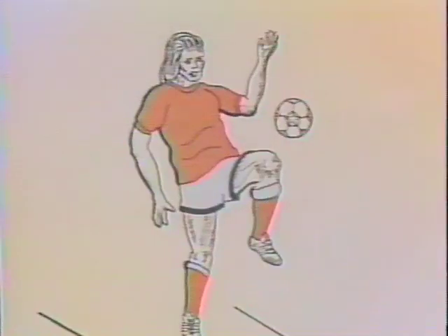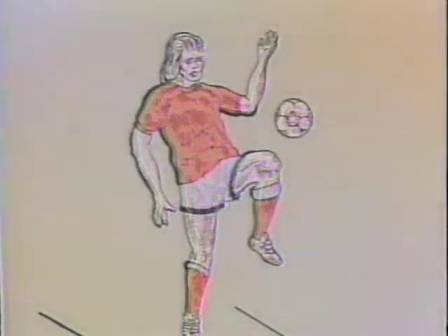Many chemicals exhibit this effect, and it's quite common. If the light level varies, then the target will change its resistance to follow the level of the light. What is important is that the target does not have a single overall resistance value. The separate molecules of the target adopt their own individual resistance value corresponding to the light falling on them. This allows the complete target to have a resistance pattern across its surface, which is a representation of the image focused upon it.